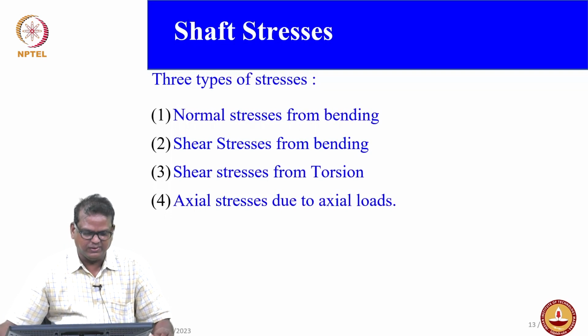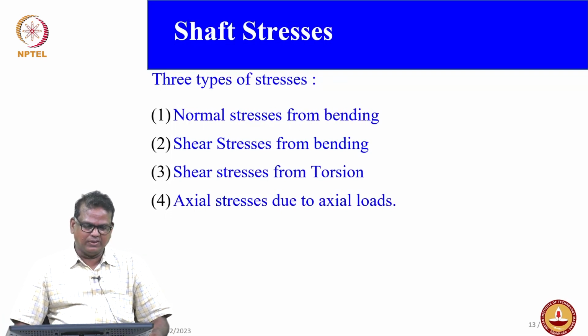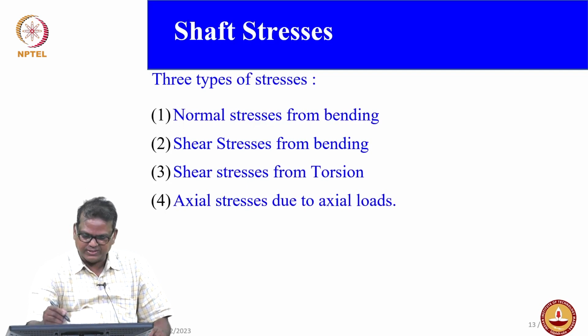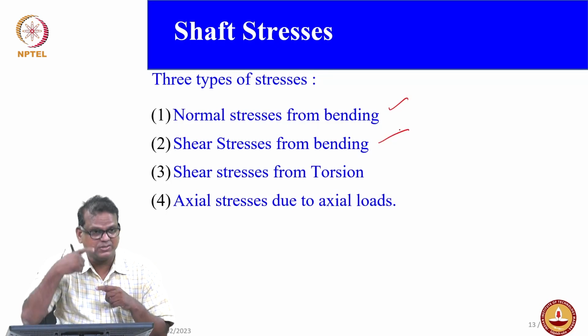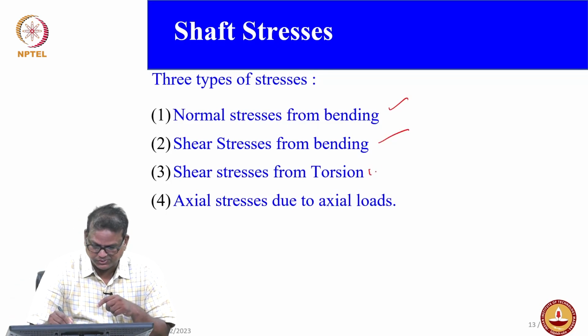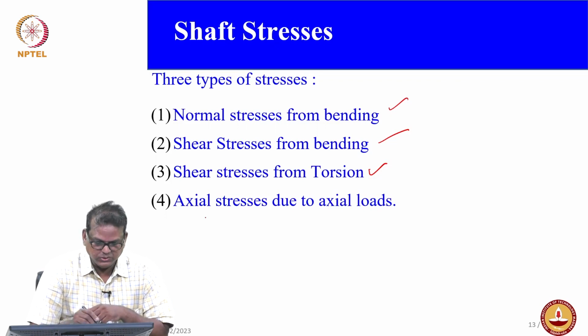Shaft stresses, okay. You will have three important stresses: normal stresses from bending, then shear stresses from bending, then shear stress due to rotation, torsion, and also axial stress due to axial loads.